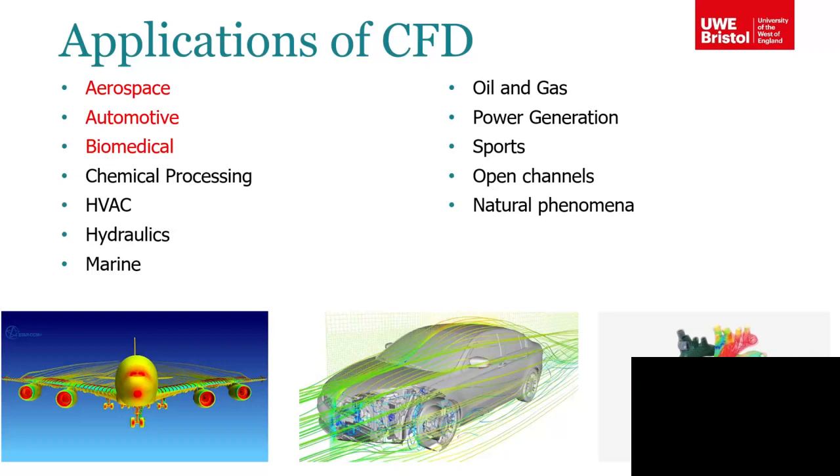And when it comes to external flows, for example, when you want to simulate the flow around this car, actually for the fluid, the car is external to the fluid, because what you are doing is you demarcate a large domain outside the car, and then put the car inside, and then deduct that car from that square domain.